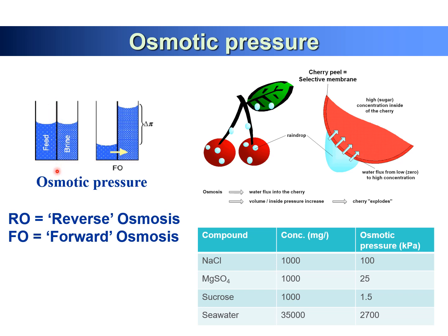When you have this condition, pure water with low salt concentration will pass through your membrane, and then you have a water head. Your high concentration, high osmotic pressure will suck your water molecules through your RO membrane, and then you create your natural osmotic pressure.